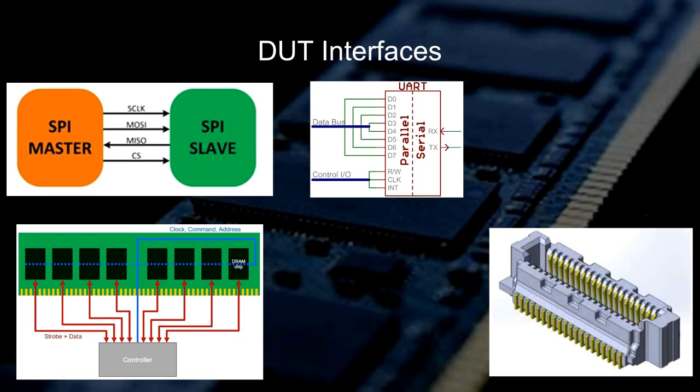Because MemTest86 needed to be purchased, MemTest86 was not considered as a part of the design. However, the individual tests from MemTest86 were considered because of the robustness of MemTest86. The algorithms included in memory testing include walking ones, own address, inverse address, moving inversion algorithms, random pattern, modulo 20, and a bit fade test.